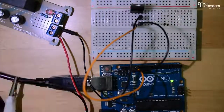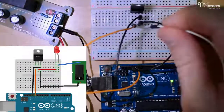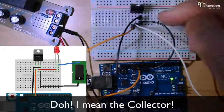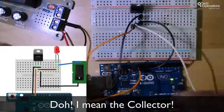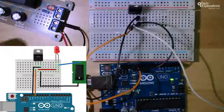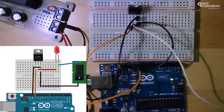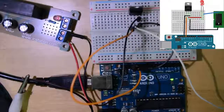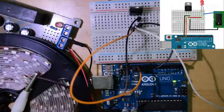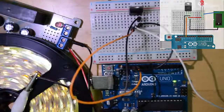Okay, now I've got the schematic here, you can see it. I'm going to plug the cathode in the collector of the transistor. The anode goes to the positive, sorry, the ground pin of the power supply. And I've got the program already running on the Arduino, so all it does is make the LEDs blink randomly. Let's have a look at the sketch.